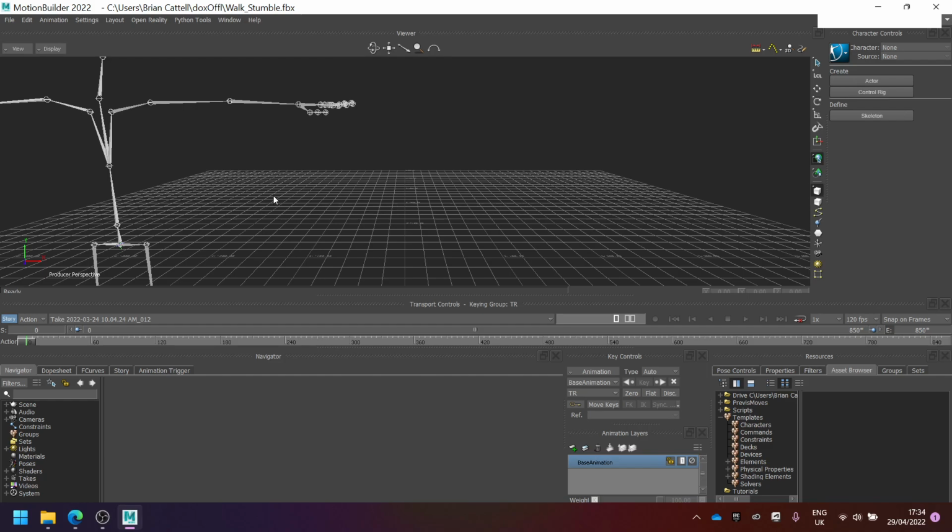So a kind of humanoid figure that can take this skeleton and data recorded onto this skeleton and have it itself. So a skeletonized character figure would be something that maybe comes from Quick Rig in Maya, but you don't need the control rig bit, so you can just put the skeleton in. A skeleton from Blender, or Rigify I think it's called in Blender. And the option I've chosen is Mixamo. And Mixamo is a really great way to get your fairly simple character skeletonized for no money at all and very little time.